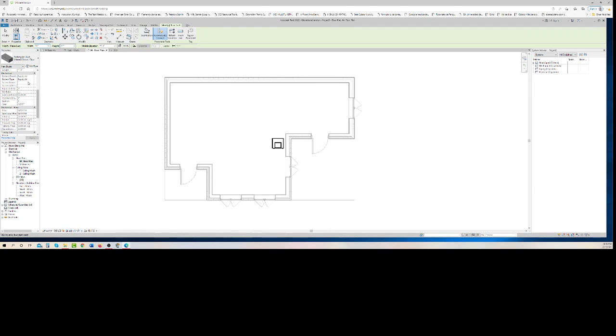Okay, and the next thing I need to do is make sure it's what we call supply air. That means we're supplying air to the rest of the building. And the middle elevation probably wants to be something like 10 feet. That gives it a little bit of room off of the ceiling, right? You can have 2x4s and rafters and joists and stuff up there. So I'm going to move it up a little bit. And it's probably going to run somewhere down the middle here. Something like that. I don't really care where it goes.